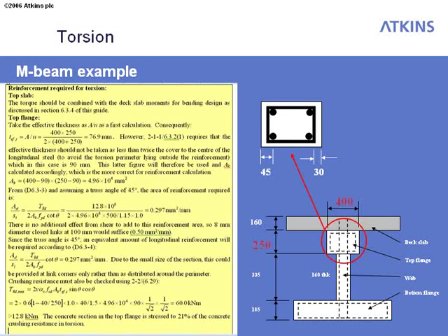It's just been set as 45 degrees, so we get the same reinforcement requirement in both directions. But it needn't have been set that way. So we get a reinforcement requirement of 0.297 millimeters squared per millimeter in both directions. That basically equates to 8 mm diameter closed links at 100 mm centres.